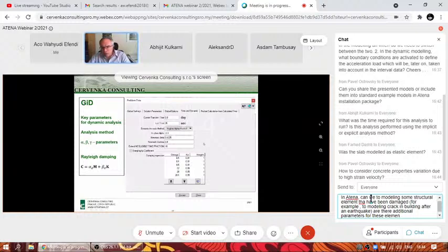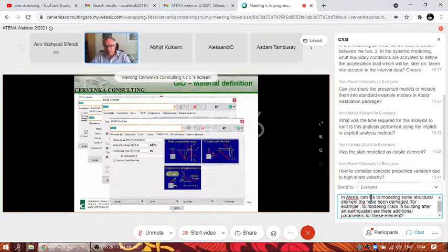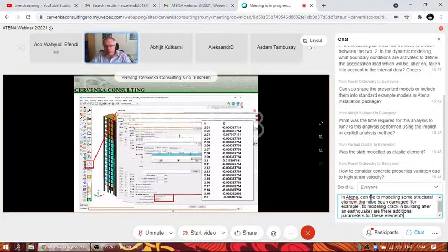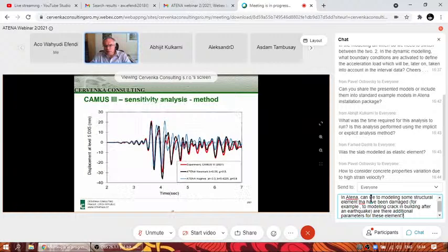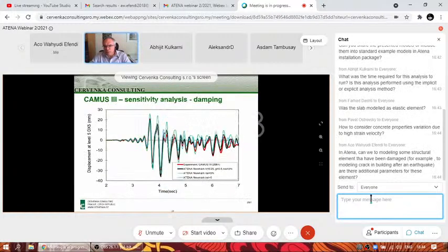So, of course, as I told you in this analysis, that's why I wanted to show that the result is not so critical. If we, for instance, look at these results, I considered here really the extreme situation that I don't consider any damping, and I consider damping 5%. Especially if you consider the result between 2% damping and 5% damping, which is the blue line and the black line, the difference is not so big.